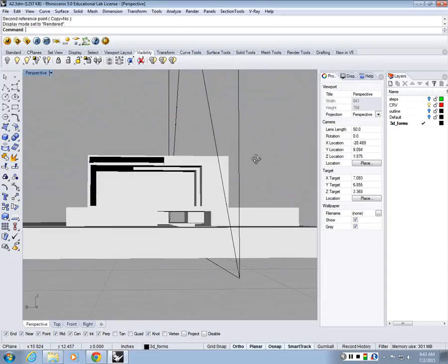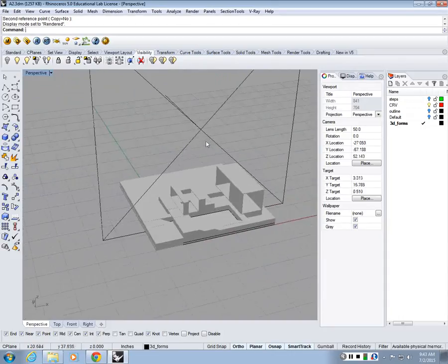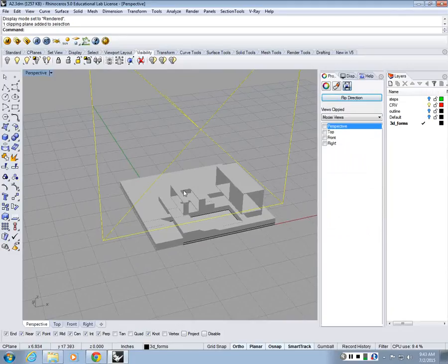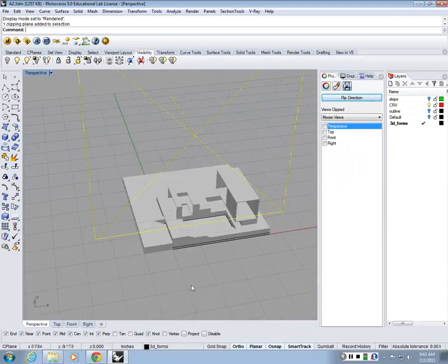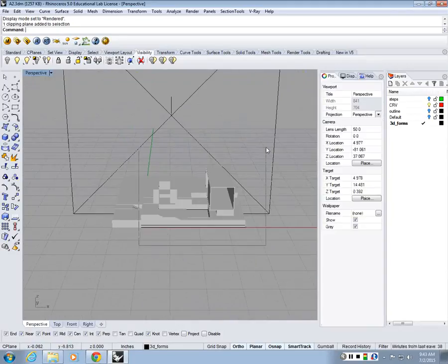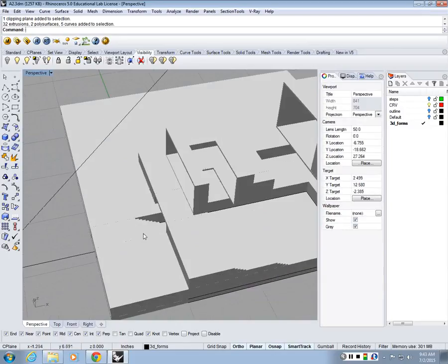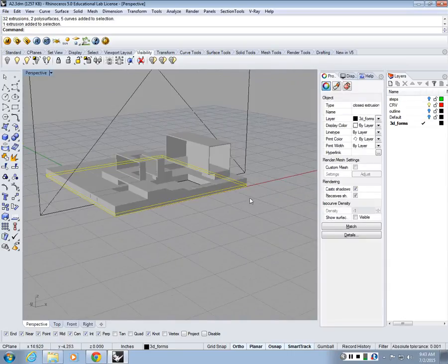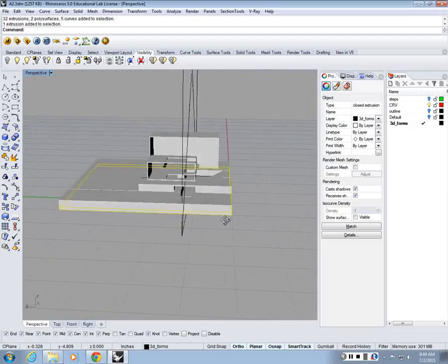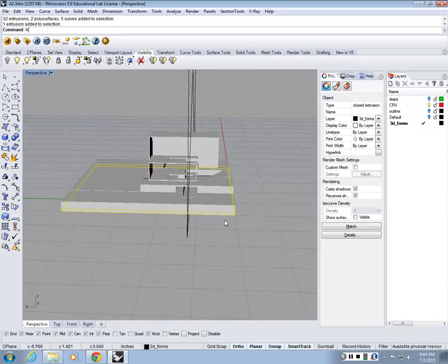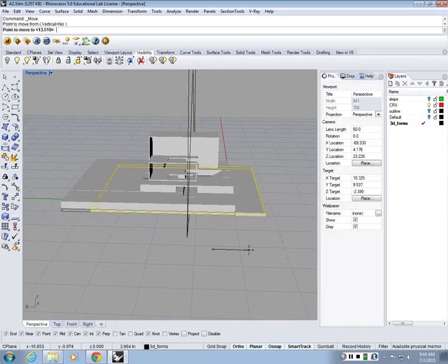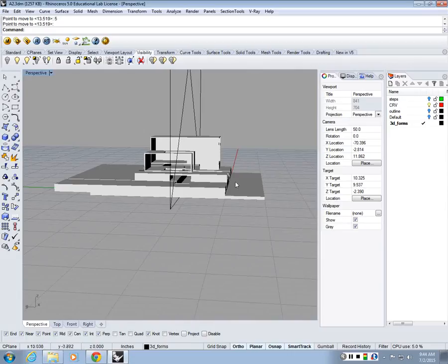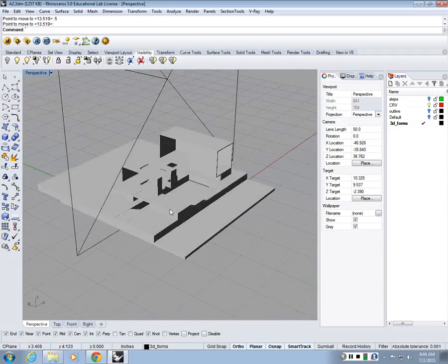Alright, so far so good? Any questions so far? Now, extend the landscape. So this guy is 13 by 18. In order to generate the full section, I just increase the landscape. I started with my base, this guy. I just did scale 1D, one way, made it 23, the other way 23. And that's what was being asked. This could actually be located here as well, so I could push it 5 inches this way if I want. And then I add the blocks here too, so it could be located anywhere you want on your drawing.